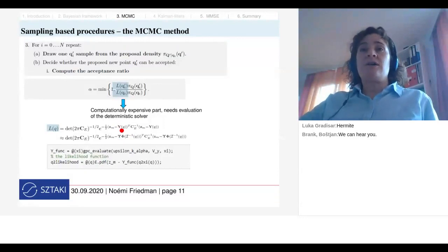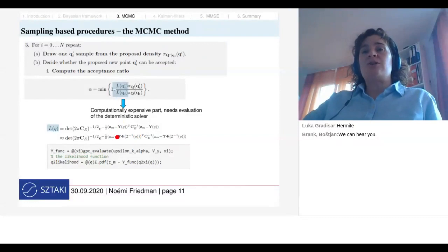So if I would need to run a FEM solver, which is very expensive, a nonlinear model with millions of mesh nodes, this is something that we cannot afford. But if you succeeded to make a good proxy model, a good surrogate model that we did in the previous lectures, then we can use this proxy model, which is right here. So this is just the Xi, my germ. So I had a PC expansion of the Y random variable that can compute my observable with the help of this surrogate model. And then it goes with just evaluation of polynomials, which goes extremely fast. So that can make a really fast random walk, okay?